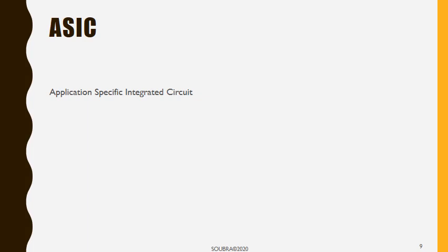All right, so let's see. Who remembers the things that I've talked about in DSD? No one? You do? Okay. So what's so special about ASIC? Not general. Okay. If we compare them to the FPGA, the FPGAs are usually reprogrammable. So basically, you can synthesize different hardware on the FPGA. Here, you do it once, and that's it. They're specific to a particular application or customer.